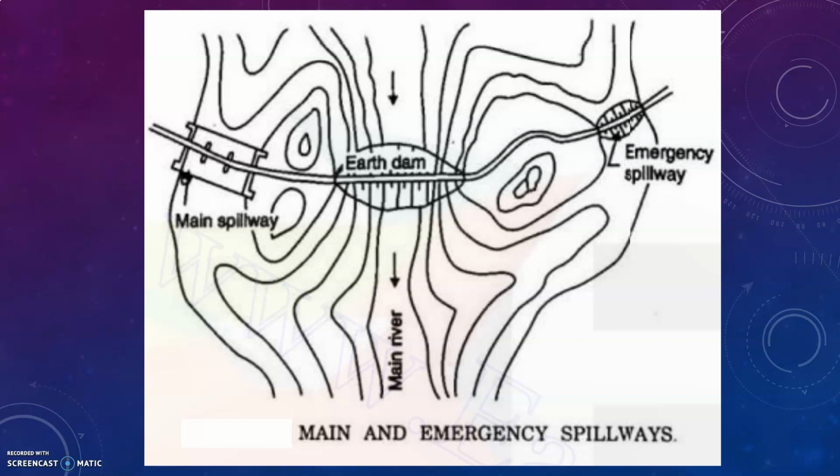Under normal reservoir operation, emergency spillways are never required to function. Their functioning is required under the situations caused by an enforced shutdown of the outlet works or malfunctioning of spillway gates, or when a flood greater than the design flood occurs. The crest of an emergency spillway is therefore placed at or above the designed maximum reservoir water surface.